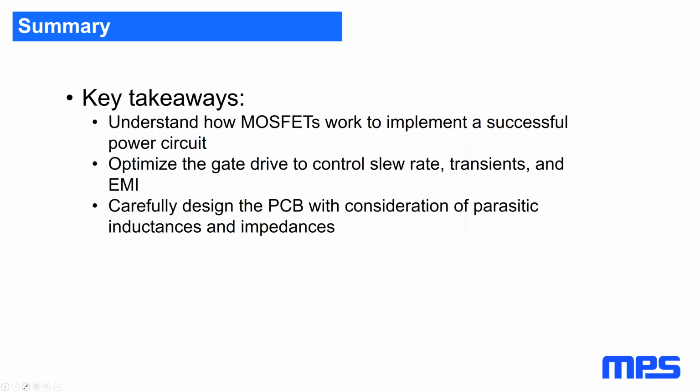So that's it for the webinar on driving power MOSFETs. Some things you should remember. It's helpful to understand a bit about how MOSFETs work and how they're made so you can design a successful gate drive circuit. You want to optimize the gate drive circuit to accomplish whatever your requirements are. Switching speed, slew rate, switching losses, and EMI are all considerations that are sometimes at odds with each other. And you also need to be careful with stray inductances and power supply impedances when you design a board.